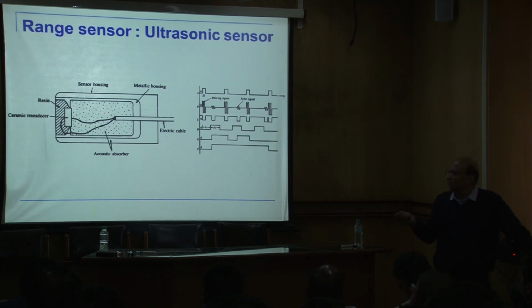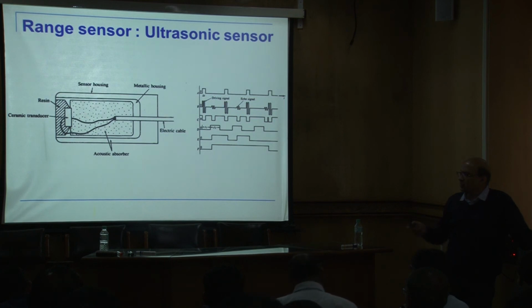This is another experiment we'll be doing today, because mobile robots use this extensively for measuring obstacles in front, for measuring any kind of obstacles that come in. The working principle is very simple. You just activate it in a particular sequence, check when the signal has come back, and from that we can figure out the distance. We have this experiment in the lab today. Using this, you can make mobile robots and do all kinds of work for motion planning, obstacle avoidance, things like that.